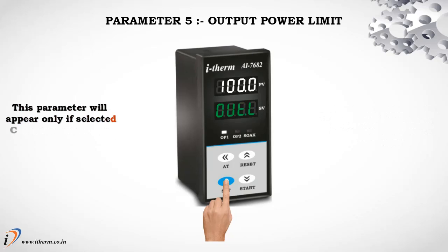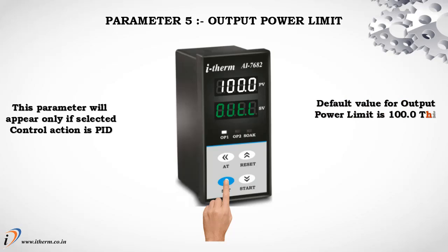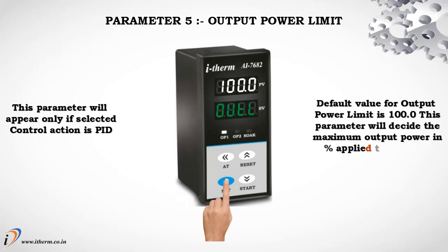Parameter 5, Output Power Limit. This parameter will appear only if selected control action is PID. Default value for output power limit is 100.0. This parameter will decide the maximum output power in % applied to the load.